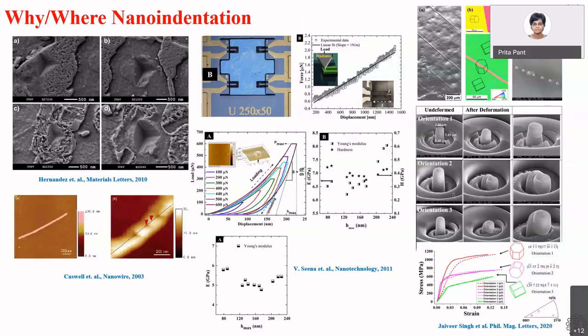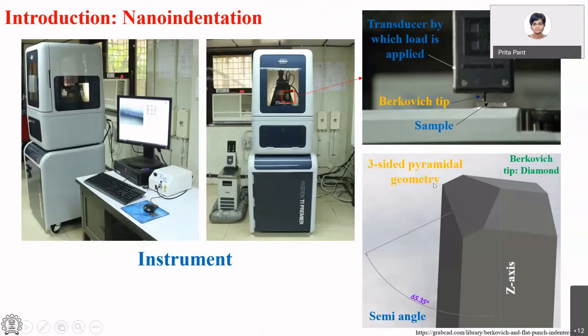Those of you who are from mechanical or engineering, where you've done a workshop, think of lathe milling, and now think of doing milling with a beam of ions and not with a tool. So this is exactly milling, where we take a bulk sample and we use an ionic beam to cut out the neighboring region, leaving a pillar standing, which is what you can see here labeled as orientation 2. And then we take these pillars and again we use this tip to compress the pillar.